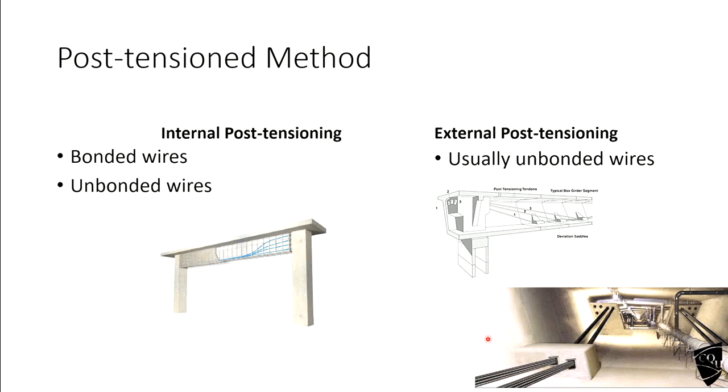Also, because of the hollow section, you should be able to put services through it. This is not pre-stressing wires, this is services, maybe electric wires or a water pipeline. So they should be able to put some services through that hollow part. So external post tensioning, especially with hollow box sections, has become more famous nowadays.